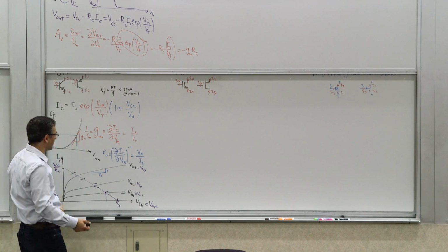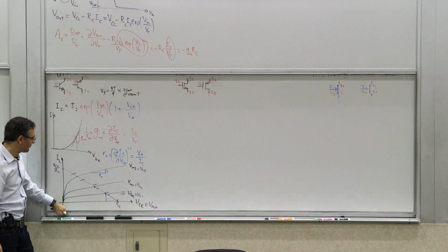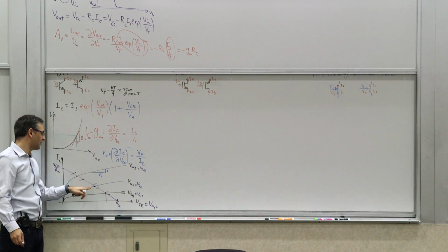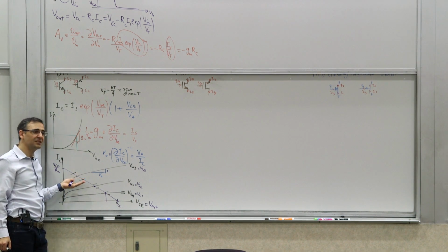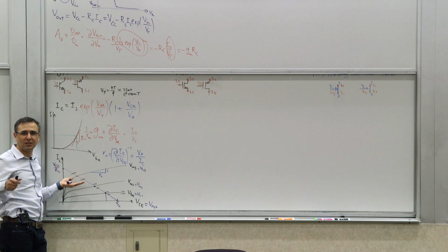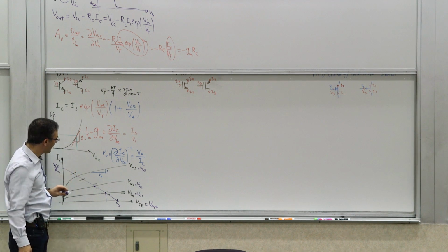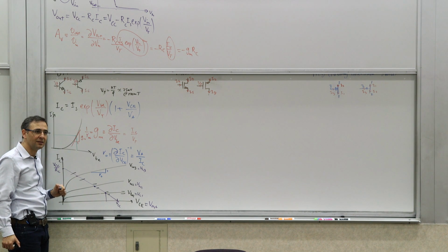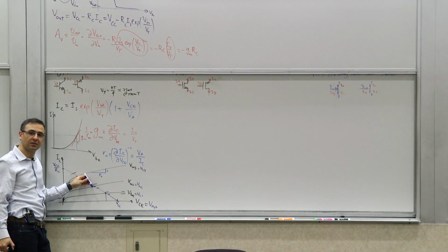This is like a large signal perspective, which is useful. But if I wanted to increase this gain, wherever it is, let's say in the middle or someplace, is there something I can do? Because a transistor is a transistor. Let's assume you're given a transistor. For a given transistor, what are you going to be able to do to make it have more gain? What do you need to do to the slope of this purple line? Make it less steep or more steep?